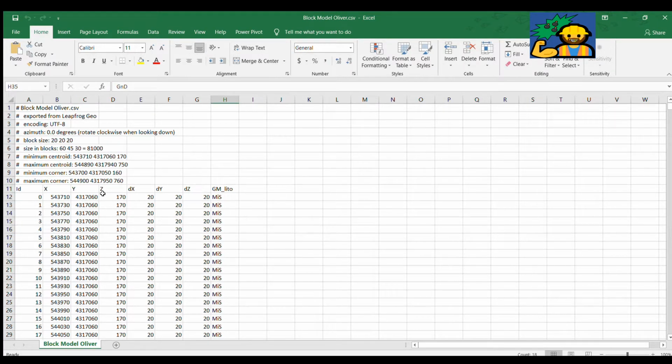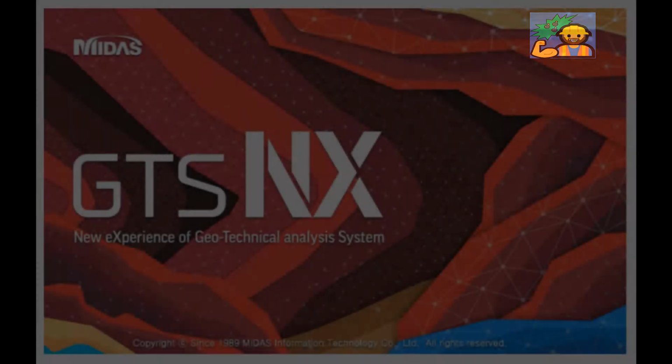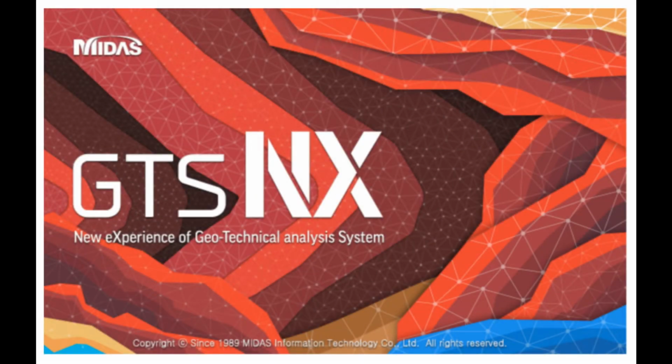Now, in order to import this into Midas GTS-NX, we need to select this part and delete it. Delete this part, and then you can export into Midas GTS-NX, and there is no need to move any rows or columns, and the model will be ready for it. As I told you in the beginning, in the last version of GTS-NX, they implemented the mining module. So now I will explain how to import the block model into Midas GTS-NX.